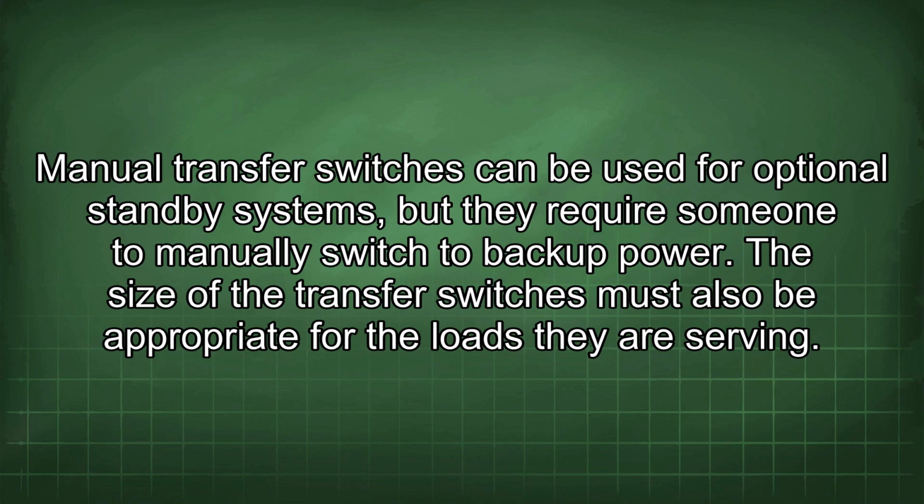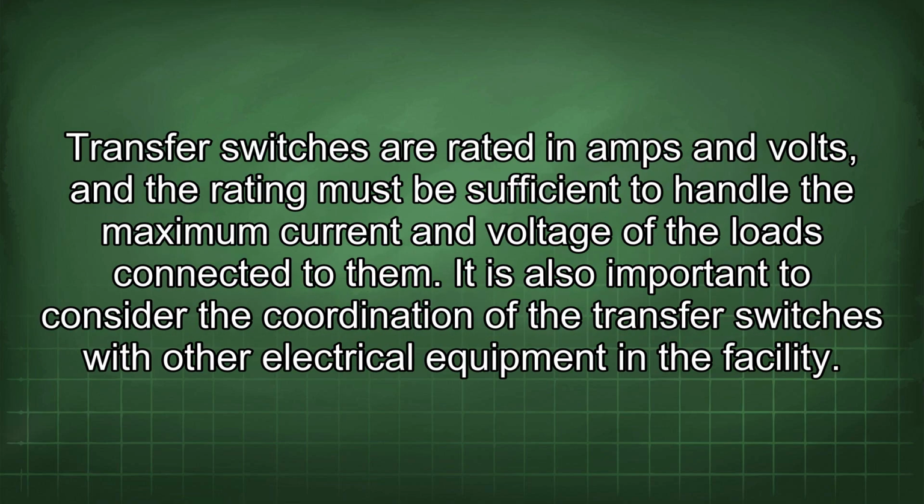The size of the transfer switches must also be appropriate for the loads they are serving. Transfer switches are rated in amps and volts, and the rating must be sufficient to handle the maximum current and voltage of the loads connected to them.